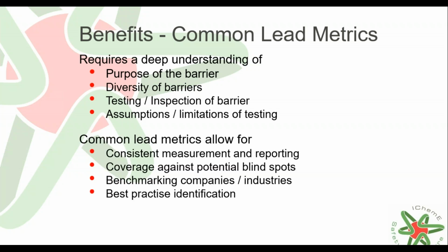Also, the assumptions and limitations are important. Making sure you understand those will mean sometimes you have to employ extra items or extra toolkits. We talked about things like X-rays or side scan UTs, all those sort of things. There's new technology available and things that you can do when you've got a particular problem. Obviously, these aren't standard things that you would do for the entire plant, but if there's an item that you become aware of, you can use it for targeted programs.